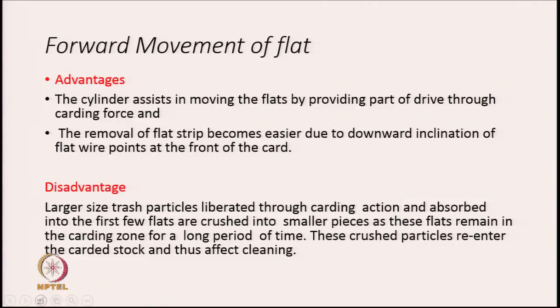The disadvantageous points are larger size trash particles liberated through carding action and absorbed into the first few flats are crushed into smaller pieces, as these flats remain in the carding zone for a long period of time. These crushed particles re-enter the carded stock and thus affect cleaning.